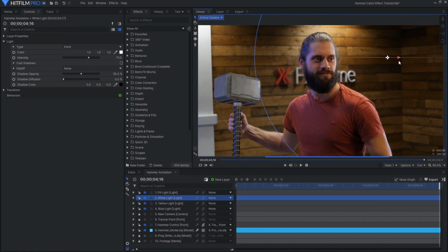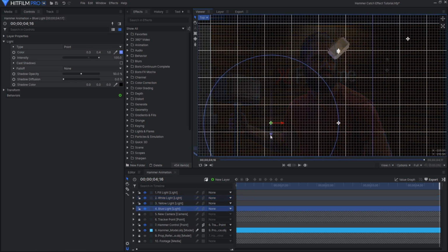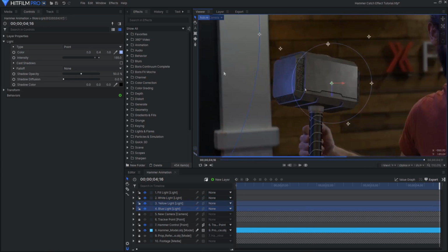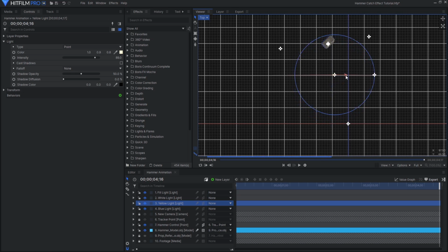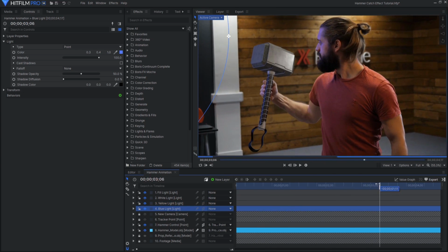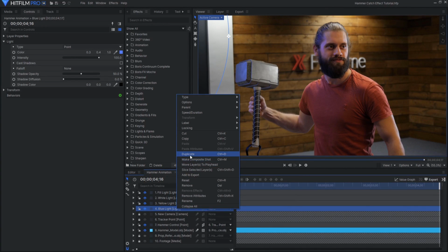You will most likely need to reposition your lights because of the different light fall-off. I recommend only using this setting to render the 3D model, and change it to one of the non-linear bit depth options for adding other effects. The light is now the right color and coming from the right directions.